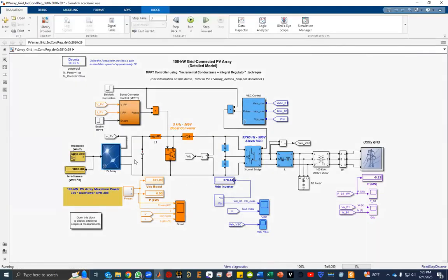We can see that the array's voltage is 249, in some cases 256, 274. It keeps changing, but we need a boost circuit, which is a step-up transformer type of thing, but for DC systems.